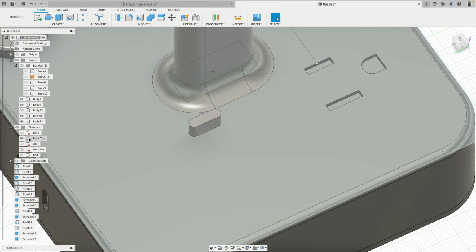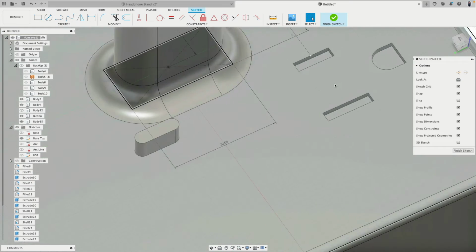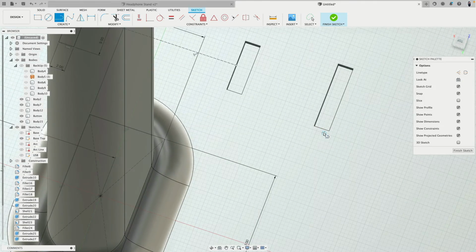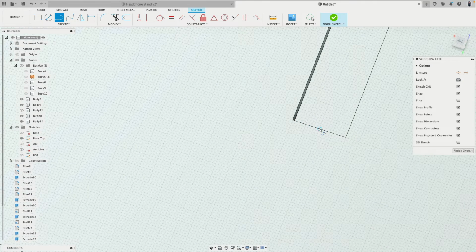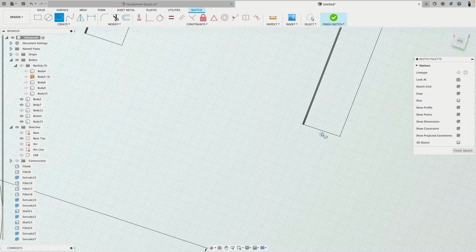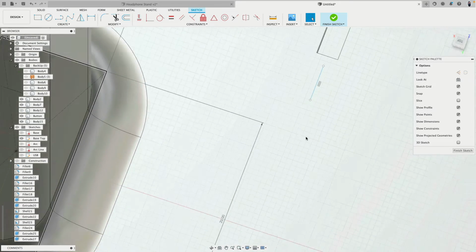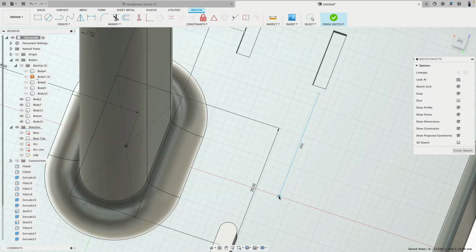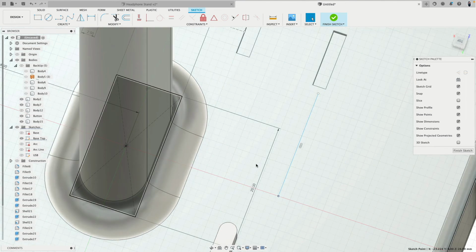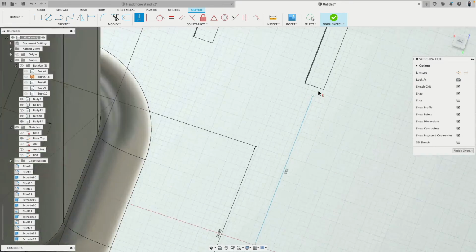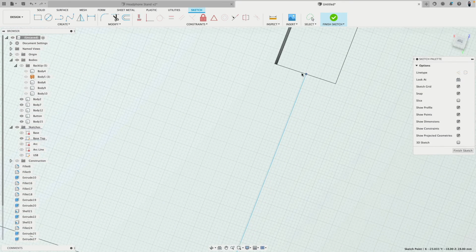So we go simply back to this sketch and then, does this line up? Oh yeah, actually it does line up. So here I could project this edge in and then use the midpoint. But I know already here along the grid, this actually does line up perfectly. So here, this point I make horizontally constrained to the world origin. And then this should be there. Sometimes the dragging is kind of cranky.